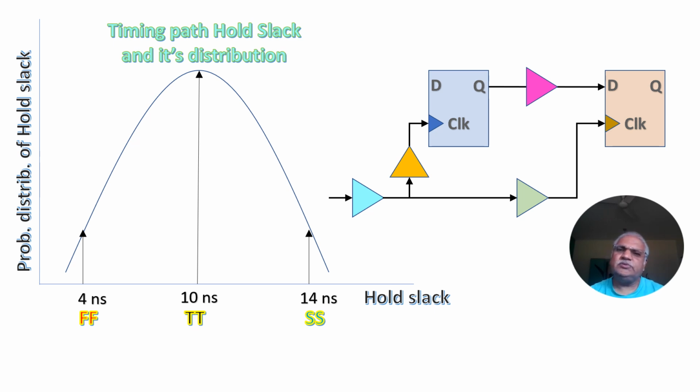If you want to see that, let us consider one timing path. In this scenario, there are different instances of different VTs and different drive strengths. This is the last common instance of the timing path, this is part of the launch clock path, this is part of the capture clock path, and this is part of the data path.